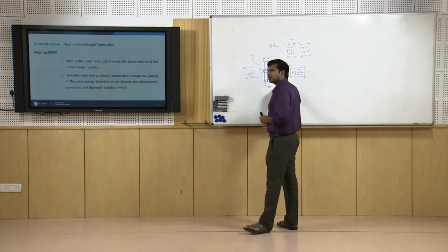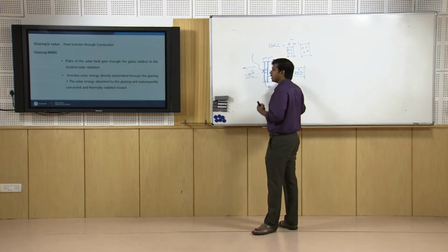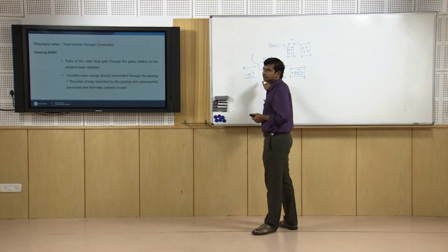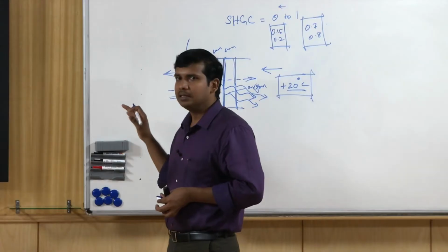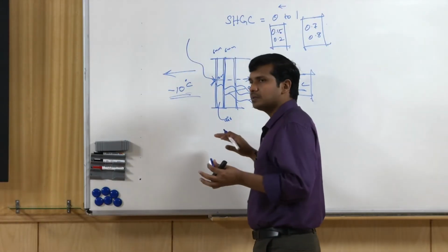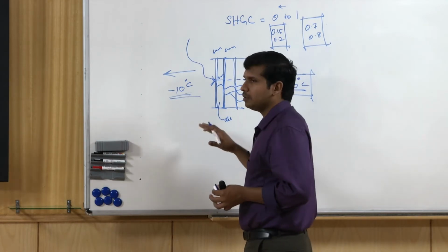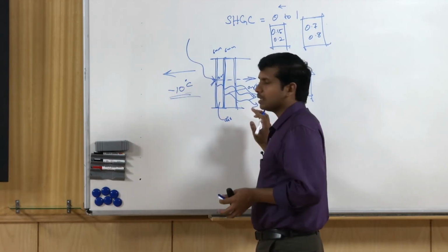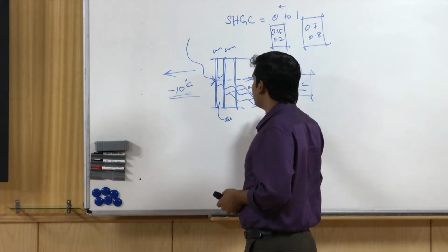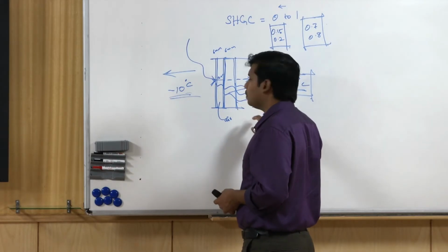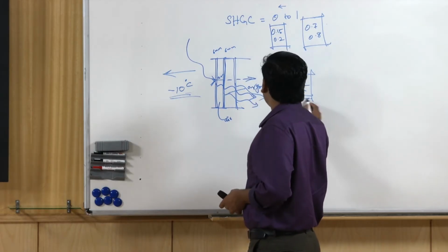On the other hand, during summers you really want more direct solar heat gain, because the temperatures are not going to go very high, except for certain extreme cases where both summer as well as winter are harsh. Mostly the summer sun is welcome, so you want more glazing surface, the radiant heat is welcome. In that case you will want the U value as a primary indicator.